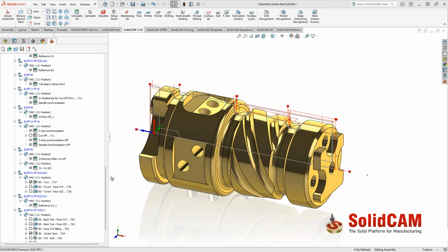And when you are using the extension collet, if you didn't tell the controller, either through the G-code or through the controller itself, that you are using the extension collet, you are going to crash a machine. So this is extremely important.